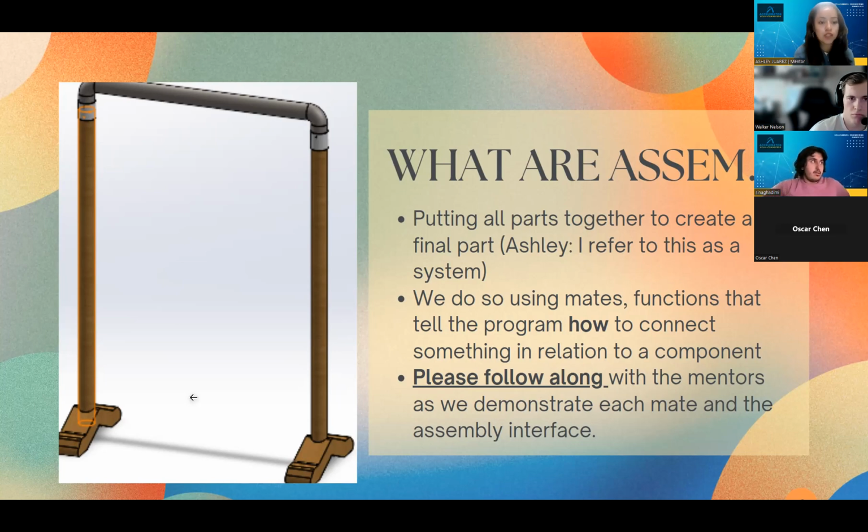The best way to do that is to orient your sketch or part in accordance to the planes. After you select that, it can either be a face or a plane, whatever serves your function. You select the feature. It has to be a feature; it cannot be something from a sketch. By feature, it could be the cut extrude, boss extrude, revolve cut, and whatnot. But that does exist. Were you having trouble using that last time, Oscar?